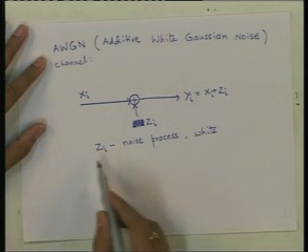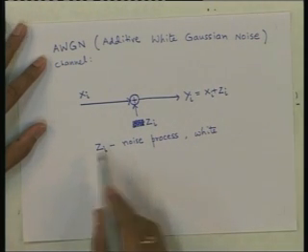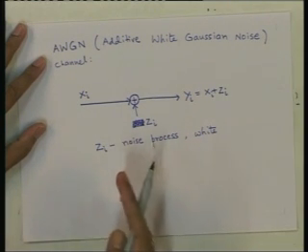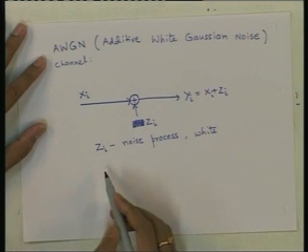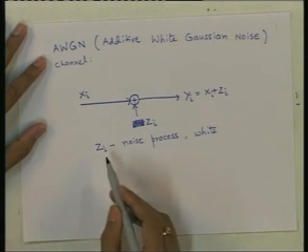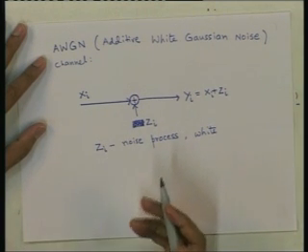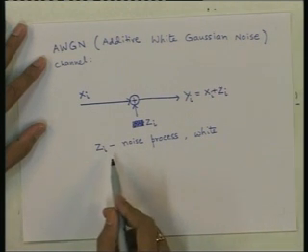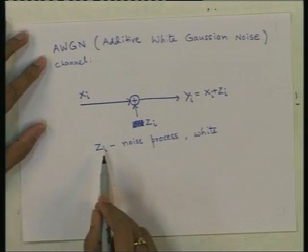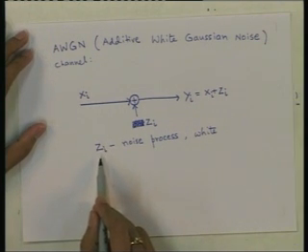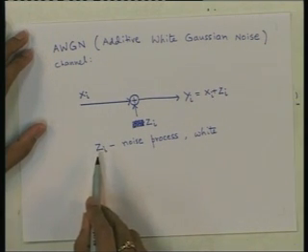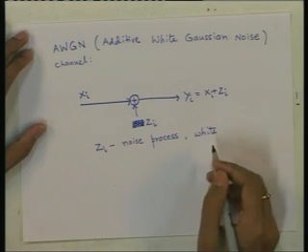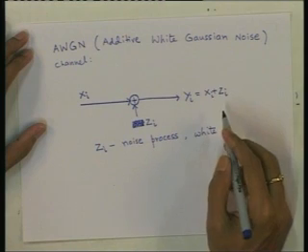The fact that it has zero autocorrelation for non-zero lags, that is, the correlation between z_i and z_(i+t) for any t is 0, implies that in the frequency domain the power spectral density of the process z_i is flat in frequency domain. That means it is white, and it is Gaussian.